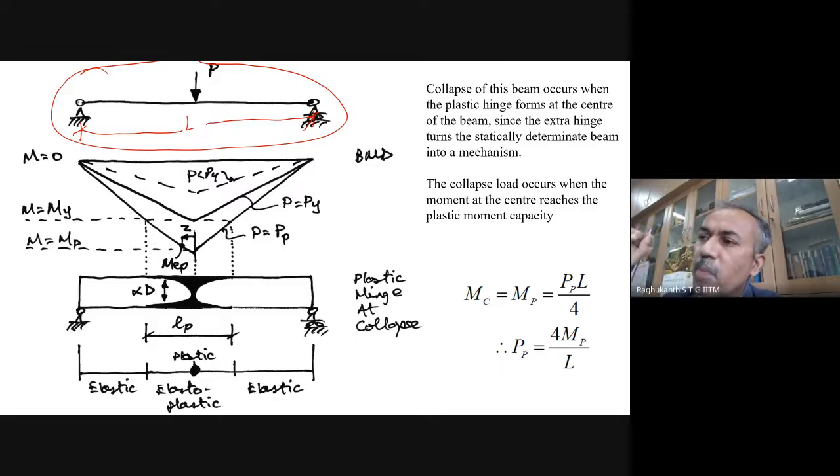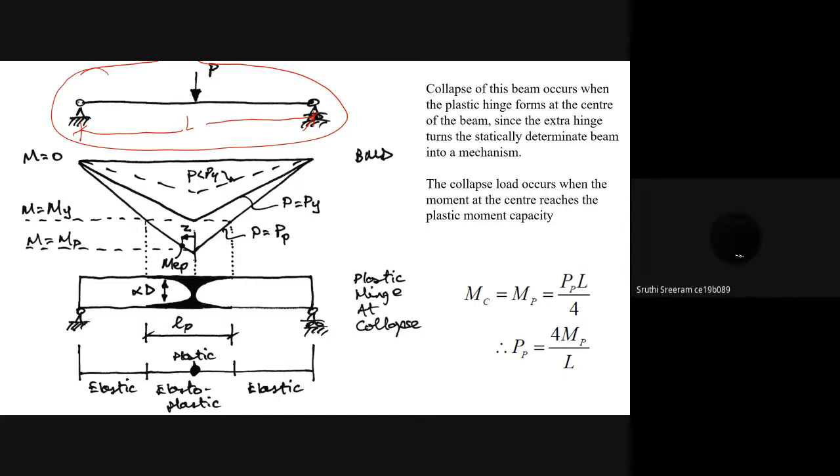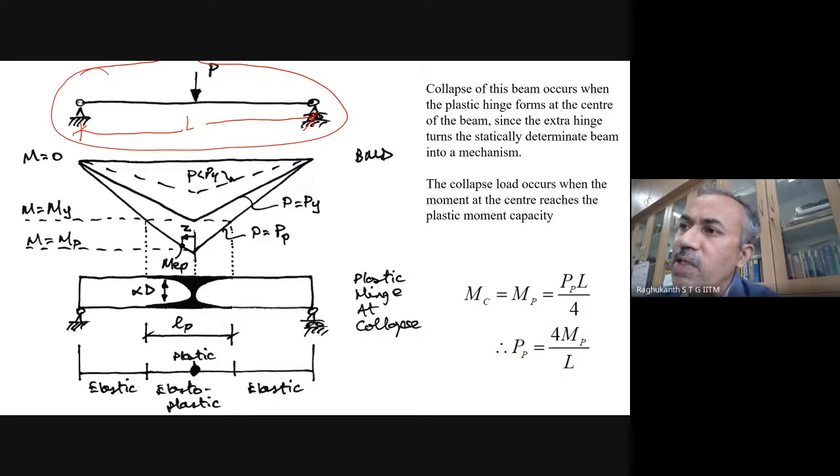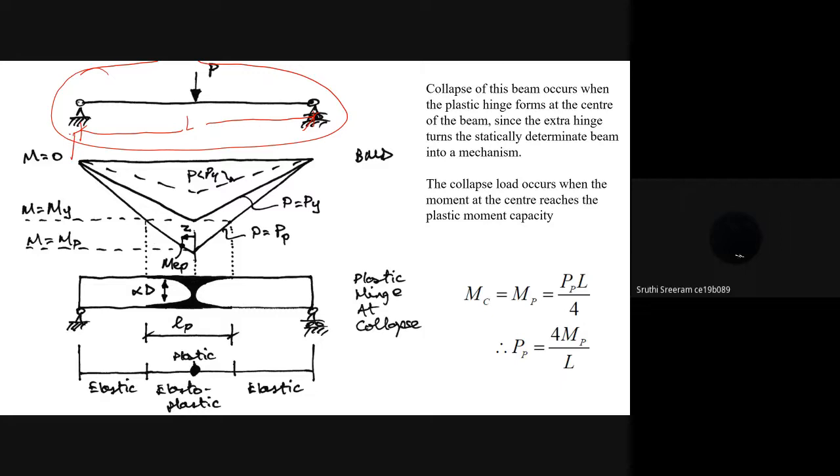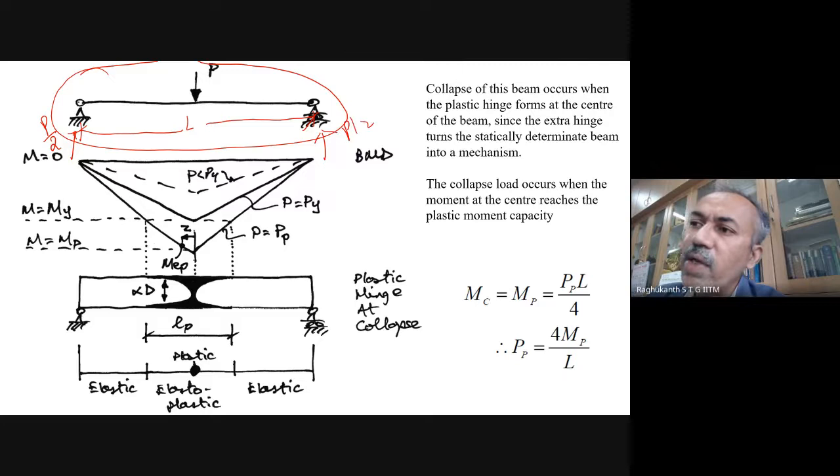For a simply supported beam subjected to a concentrated load at the center, where will the maximum bending moment be, and what is its value? Sir, it's at the point where the force is applied. What is the value, do you remember? Sir, I think PL by 4, if I'm not wrong. PL by 4 only. It's very simple. You take P by 2 and multiply by L by 2, so PL by 4 itself. So that is the maximum bending moment.